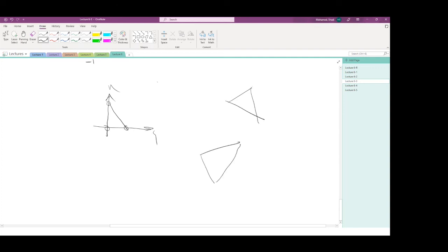You don't have to stick with the original one. You only need to have the coordinates, so it is x1, y1, x2, y2, and x3, and y3. You insert this into the Jacobian, and then the Jacobian will give you the new stiffness matrix.